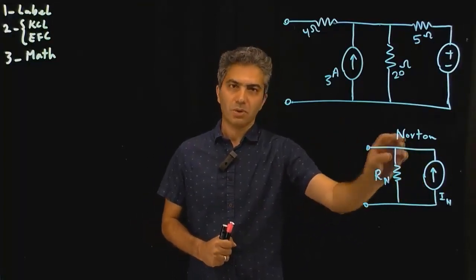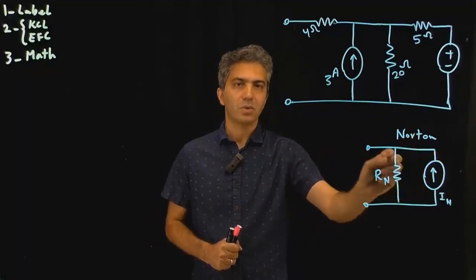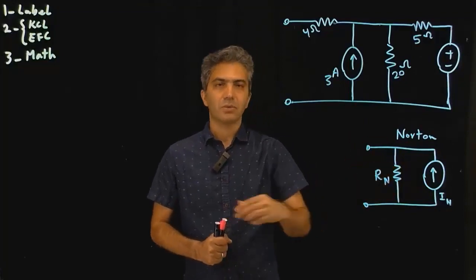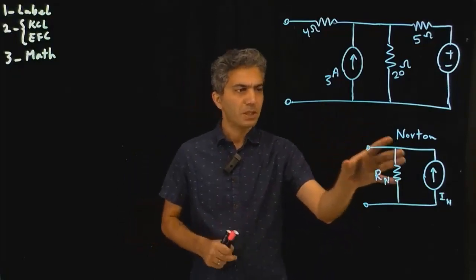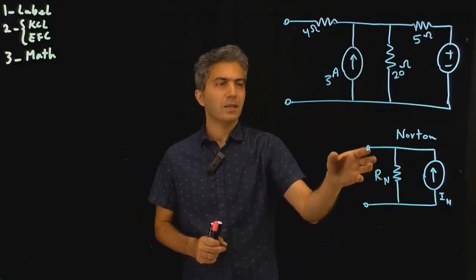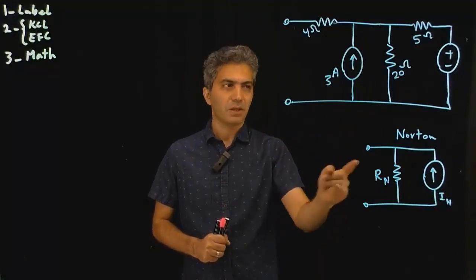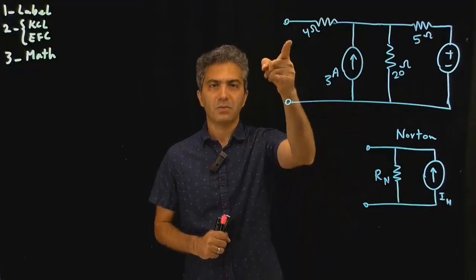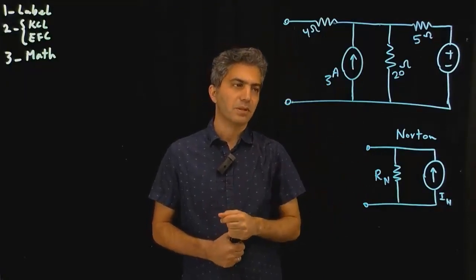So a voltage source with a resistor in series, and in the case of a Norton model, it's a current source with a resistor, or impedance for that matter, in parallel to the current source. Now, our approach was that we assume this hypothesis is true, and then we go by the very intuitive assumption that if these two are equivalent to each other, whatever is true about this circuit has to be true about that circuit, assuming the situation for both is the same.